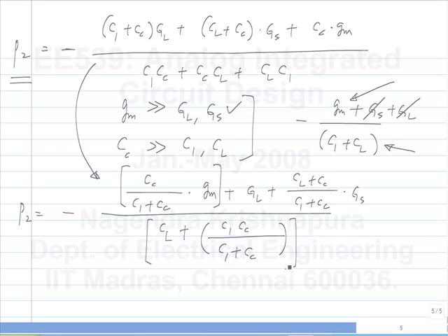As usual, it is some conductance divided by some capacitance. So the question is, do you see the conductance somewhere and do you see this capacitance somewhere? What is the denominator? So C1 and Cc are in series and the series combination is in parallel with Cl. Is that there in the circuit somewhere? That is how it is in the circuit, right?